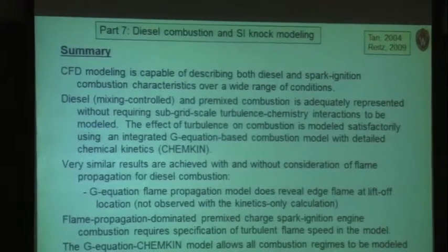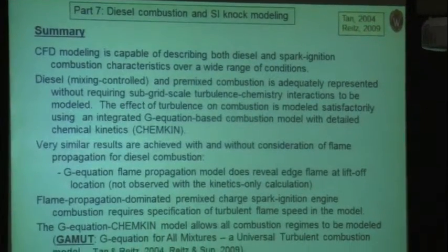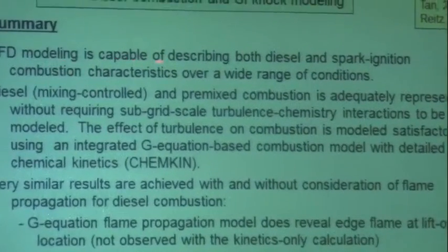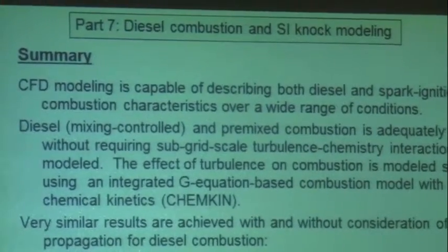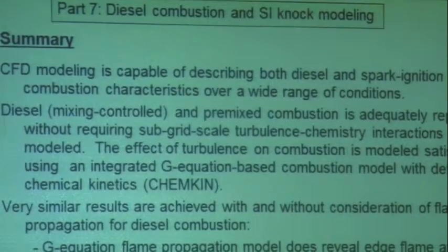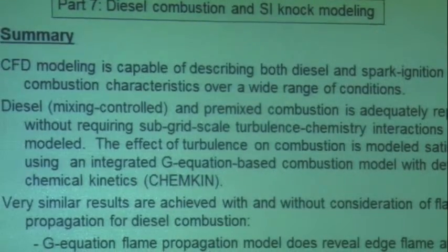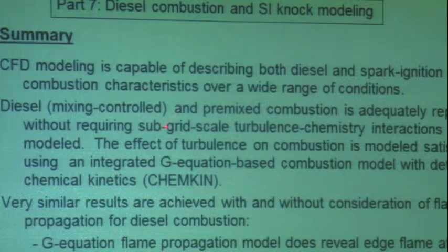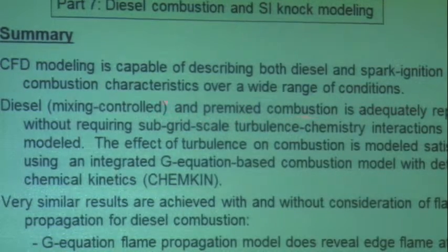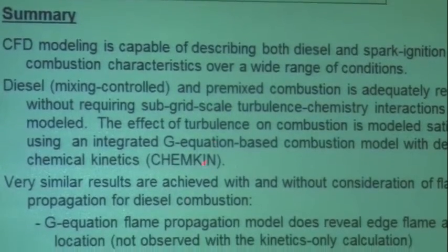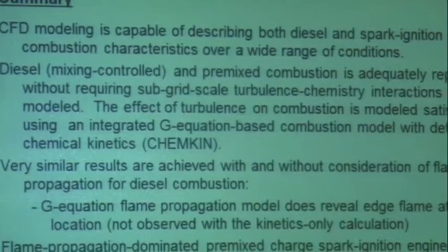So to summarize then this section of the presentation, I think I've shown you that CFD modeling is capable of describing both diesel and spark ignition combustion characteristics over wide ranges. Diesel combustion, basically mixing controlled, and pre-mixed combustion can both be represented in the models without using subgrid scale turbulence chemistry interactions.